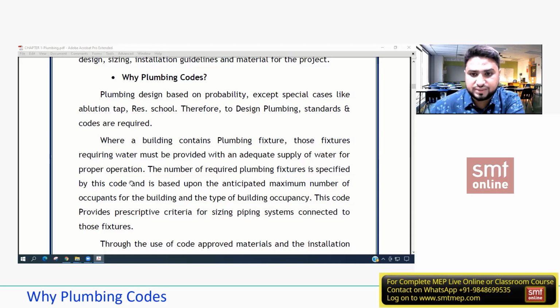So we are assuming an example for the shower. In a shower, we require a sufficient or adequate amount of water, that is, a sufficient amount of water which can come out of the shower, in terms of GPM or LPS, that is gallons per minute or liters per second, whatever it might be. I denote that as Q. Q is assigned here for flow. Always remember, in plumbing, Q is nothing but the flow or the discharge.